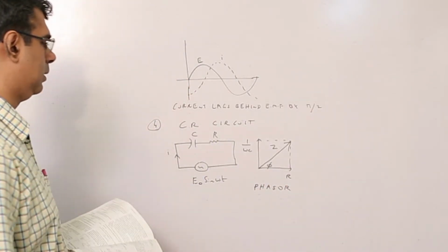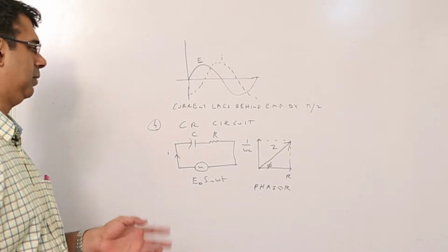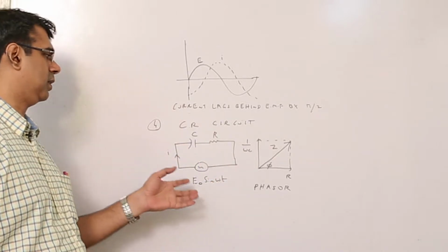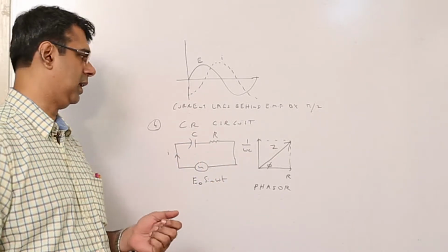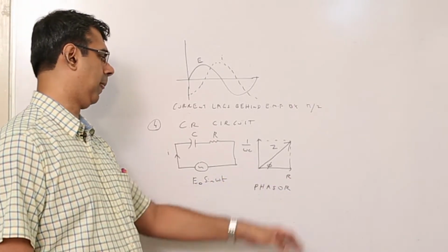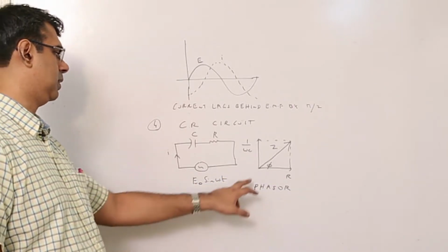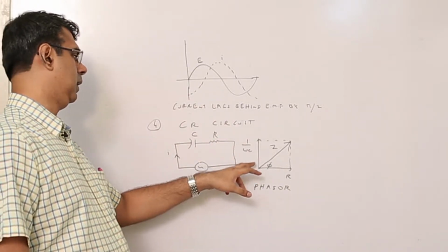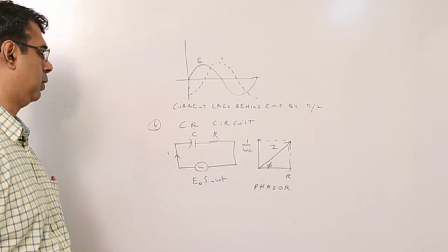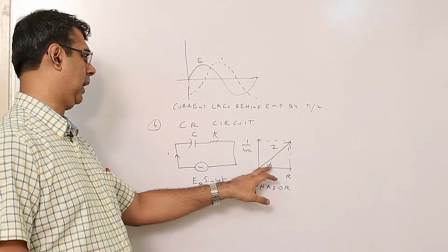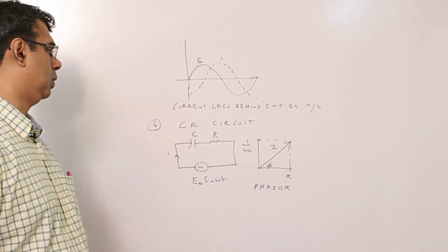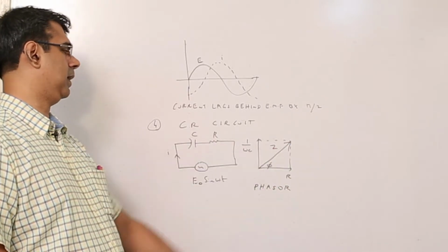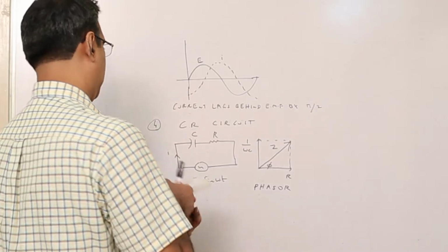So phasor, combination of phase and vector, but we cannot truly call all the quantities discussed vectors because this chapter deals only with scalar quantities. So the phase of the current across the resistor is represented by this arrow. The phase of the current across the capacitor is represented by this arrow. And you can see that the angle is 90 between them. So the phase of the resultant of these two will be represented by the diagonal of the rectangle, and in